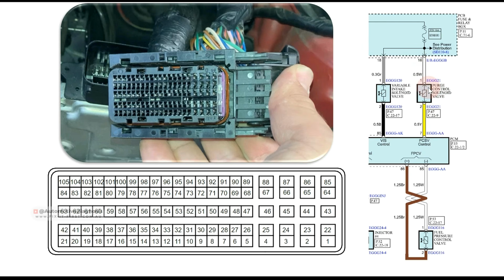Just imagine that you have an issue where the valve itself and the power supply are all okay. You think that there might be some issue on the control line, but you cannot come to a conclusion that this wire is bad before making any measurement. You need to find the wire and inspect it. For finding the wire, you need to find one end on the valve itself, which is of course really easy because on the valve we have only 2 wires, but the other end of the wire is inside the PCM connector, and it's going to be a little hard and confusing to find it right here.